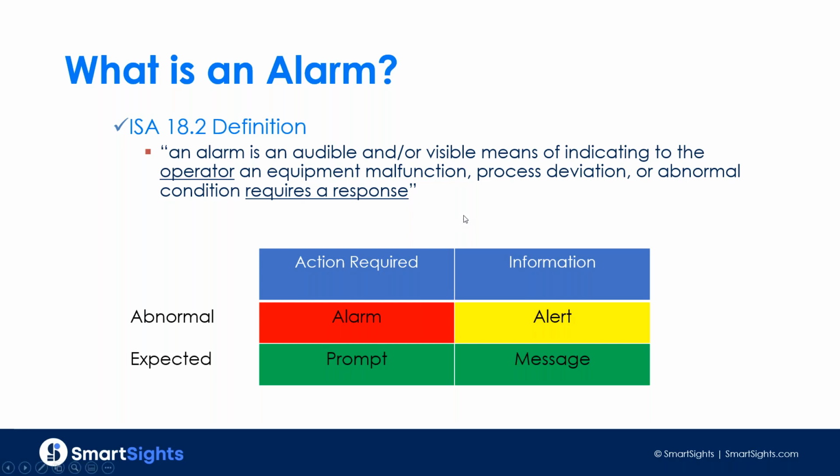So there are the concepts of abnormal and expected conditions, the concept of whether action is required or not. And you're getting into semantics, of course, but it's important to understand these things, that an alarm really is only the condition where something is abnormal and actually requires a response from the operator.